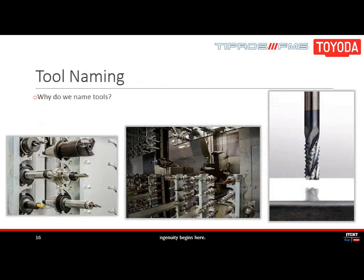Tool naming conventions should be put into place before you even start to program parts into the cell. For example, you can name tools as number 1, 2, or 3, and so on until you ran out of pocket numbers. But instead, why not use this system to give tools a unique name so that you can track the tools throughout the cell? Now the name has, in this case, a distinct meaning and can be found easily when you need to set a new part.